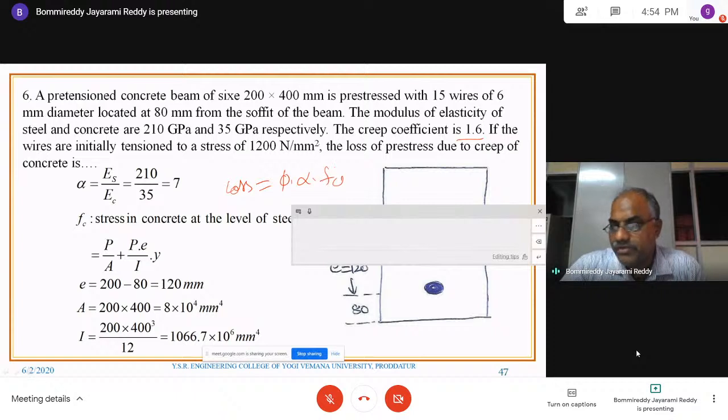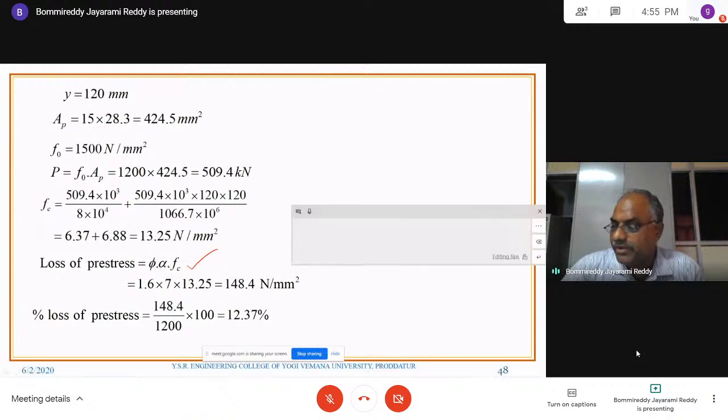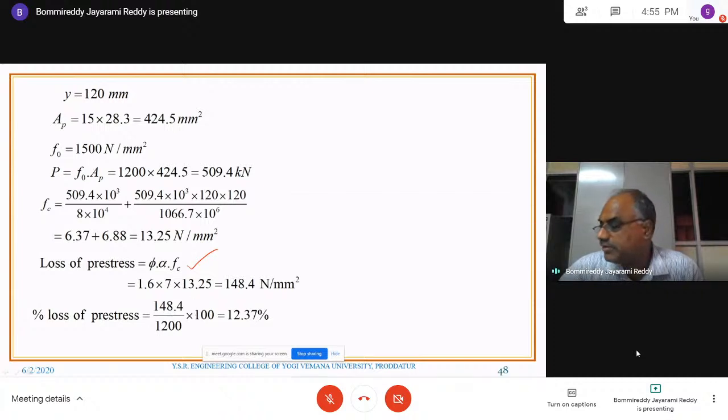Already Fc value you know, alpha value is known, phi is now 1.6, just multiplication. So this entire procedure is repetitive. Ultimately, this is important: phi alpha Fc, and multiply it. If necessary, find out the percentage of the loss of pre-stress due to the creep of concrete.